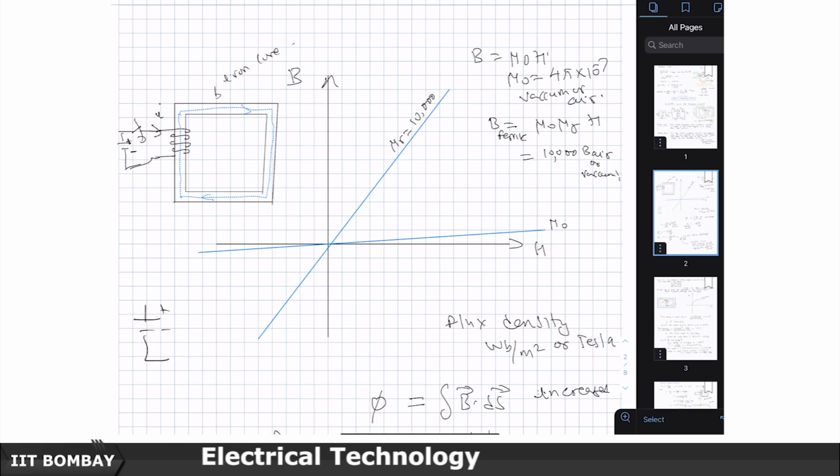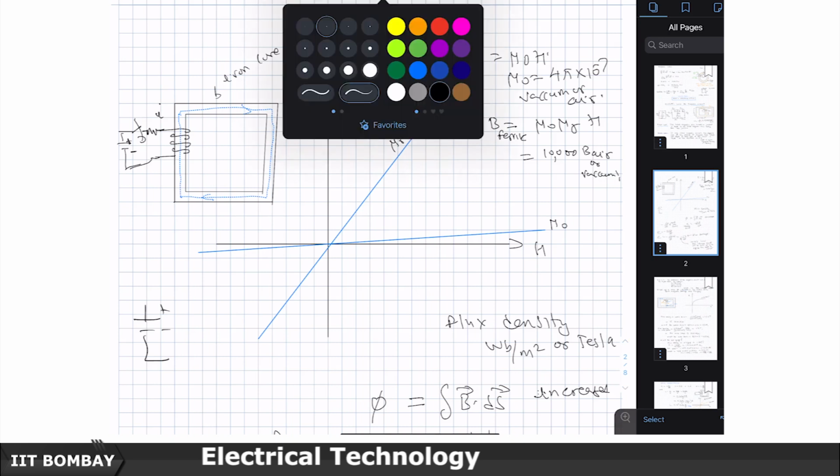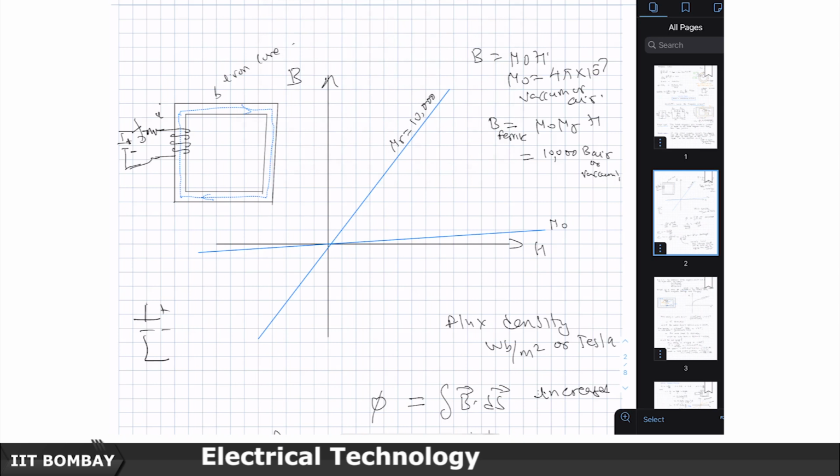Let us say that somewhere here there was also a resistance. Usually there would be some resistance, you cannot have paths which are free of resistances unless you use superconductors. Then you would have a resistance like this, and following the same convention, we will assume that all voltages which are either induced or applied, they are all additive in nature, then this is the induced EMF.